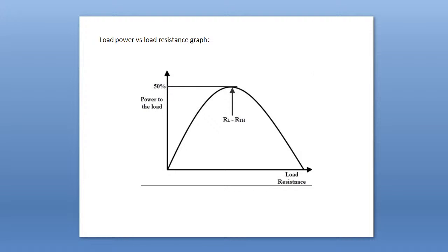How do we overcome this heating effect problem? If anyone can answer this question, okay, let me tell you the answer. If you consider the value of the load resistance to be higher than that of the source resistance, or Thevenin resistance of the circuit, we can overcome this problem.